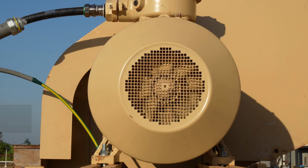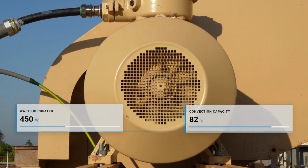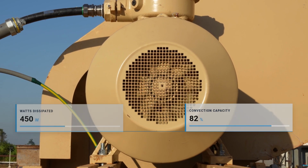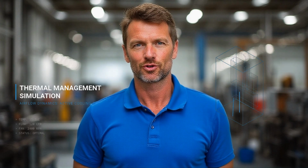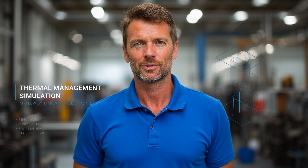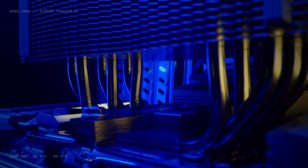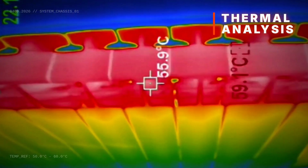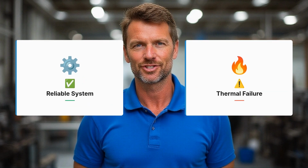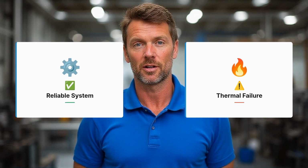First, motor cooling. You can enter your motor's power dissipation, and the calculator tells you whether convection alone is sufficient to keep it cool. Second, enclosure design. If you're sizing ventilation for an electrical panel, this tells you whether passive airflow is enough or if you need to add a fan. Third, heat sink evaluation. You've mounted a heat sink on a driver board and you want to verify it's actually doing its job at the expected ambient temperature. Every one of these scenarios takes about 30 seconds to check, and the answer is the difference between a reliable system and a thermal failure.